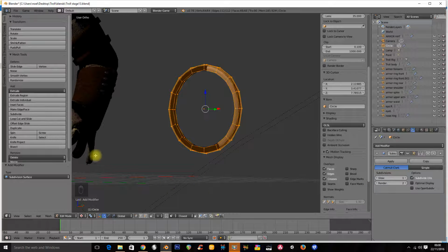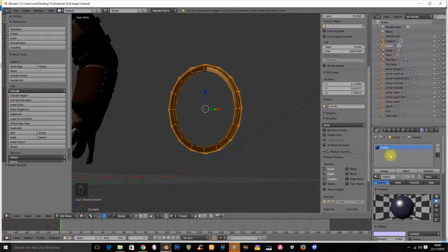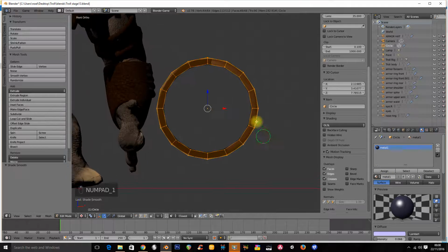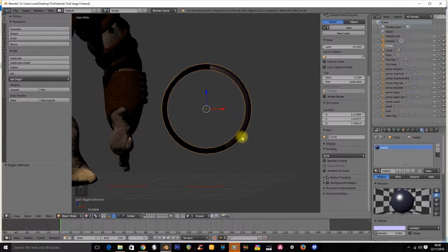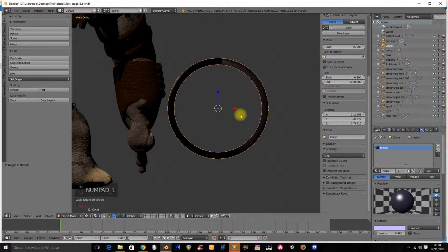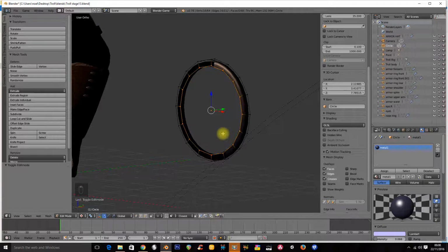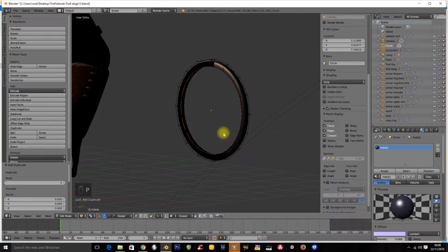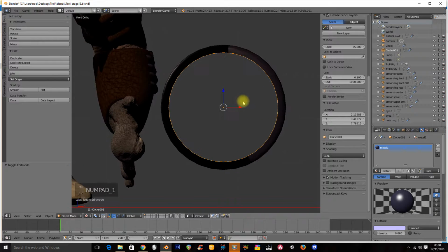I'm going to stick a subdivision surface modifier on it, set it to be smooth, give it the metal material, and that's fine for now. So there's my metal outside. Now I'm going to take this here, and I'm going to go Shift D, and then P, separate by selection. So now I have this outside, and then I have this inner piece here.